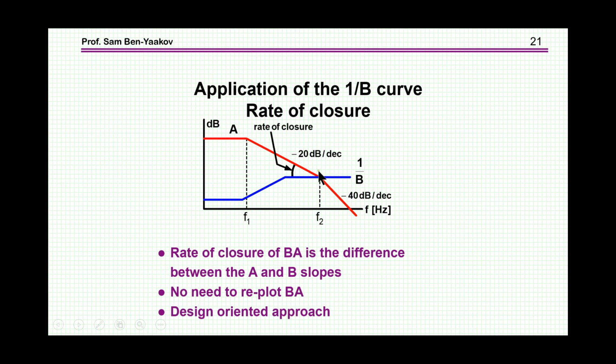So therefore, this is a system with 45 degree phase margin. You can say immediately, okay, of course, assuming that this breakpoint and this breakpoint are far away. If not, we'll have to do some more analysis, maybe simulation, to find out the exact phase margin and to do some trimming.